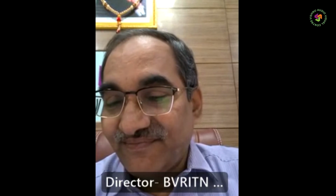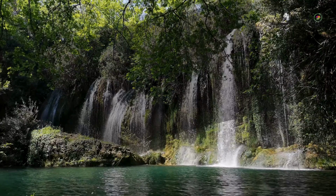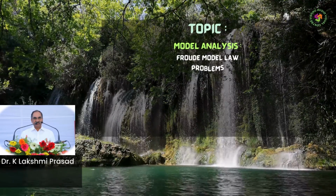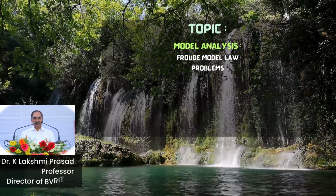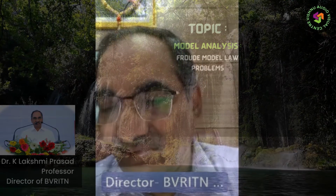Once again, between the dimensionless numbers and model analysis uses, there is one more topic called similitude. That means what type of similarities should exist between the model and the prototype so that the results predicted in the model can be applied to the prototype. So there are three types of similarities: geometric similarity, kinematic similarity, and dynamic similarity.